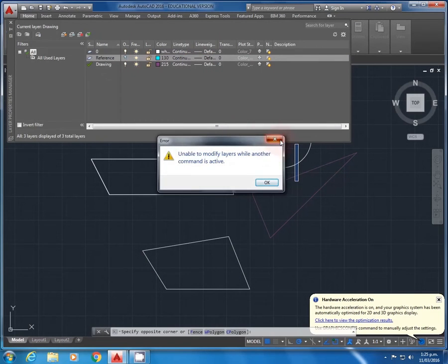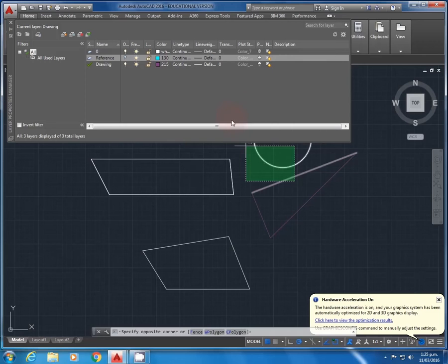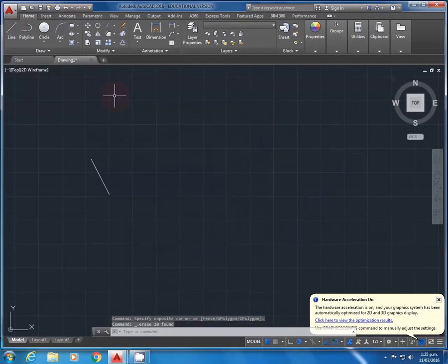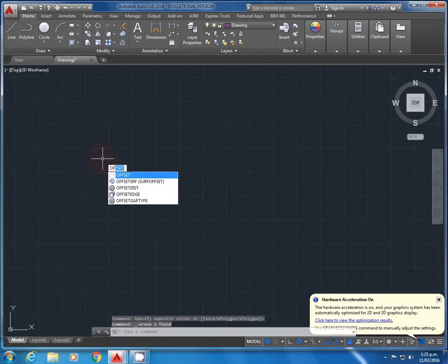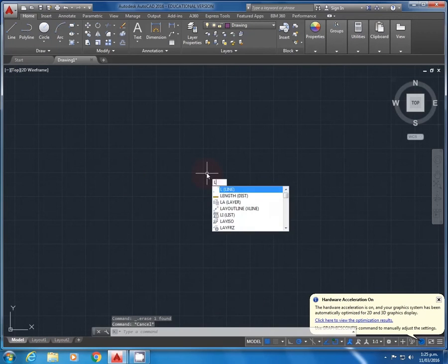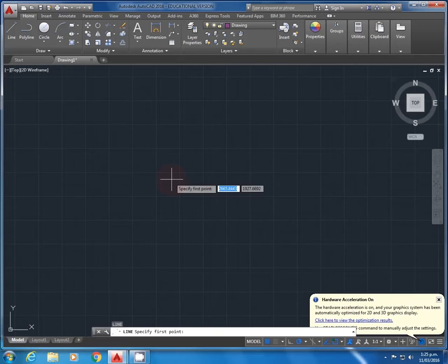So next I'm going to show you some tools on what you can actually do in AutoCAD. One of the main things that might be useful is called offset. Offset is triggered by the O command, and it's this one here. This will be really useful for planners later on, if you're doing walls or anything that requires multiple lines from a certain distance.